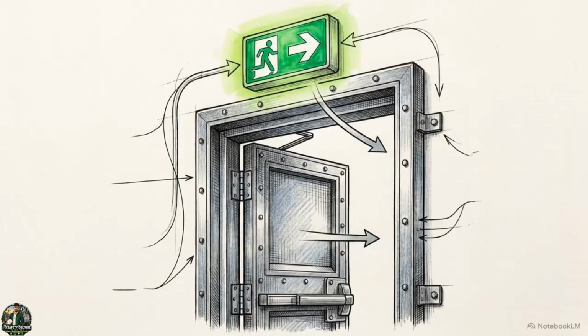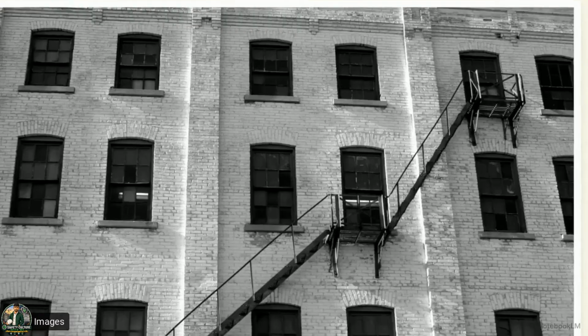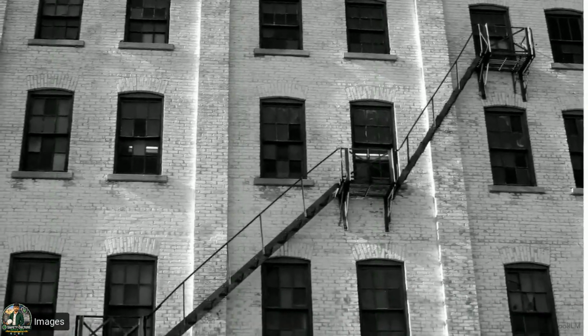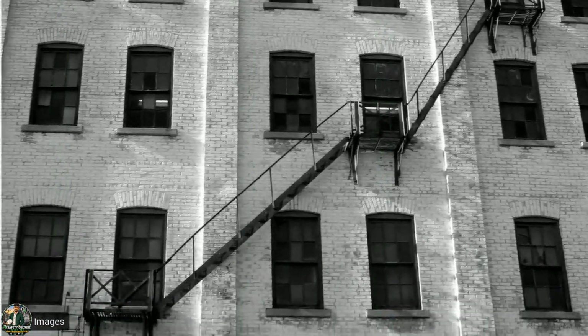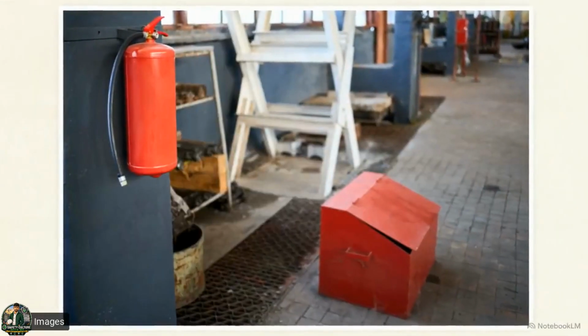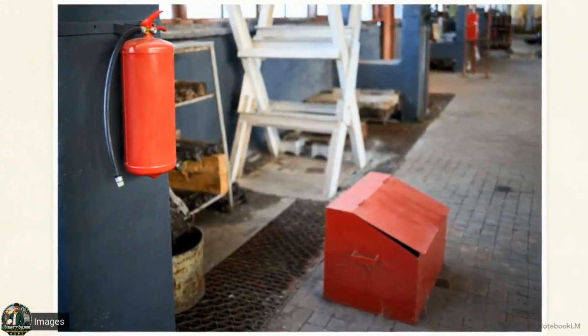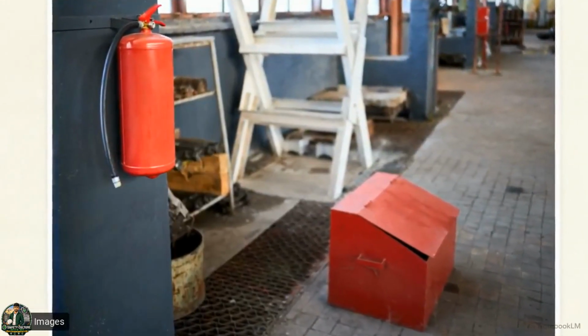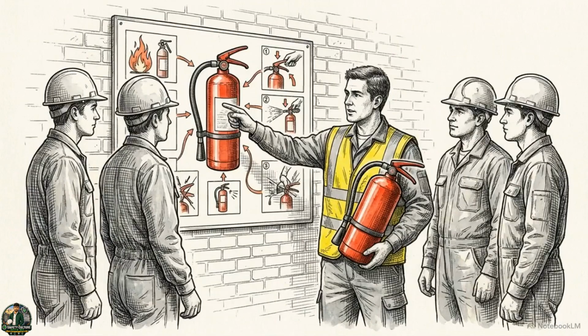Subsection 1A requires safe means of escape for all persons in the event of a fire. This demands robust, dedicated egress routes that remain structurally sound both internally and externally. Subsection 1b and subsection 2 mandate the physical presence of extinguishing facilities and require management to ensure all workers are adequately trained in the exact routine to follow when a fire breaks out.